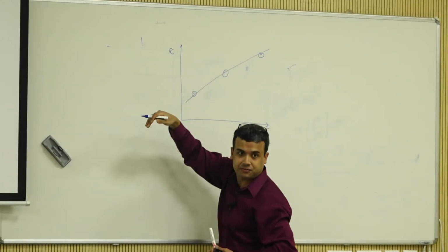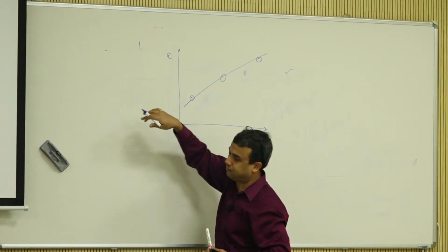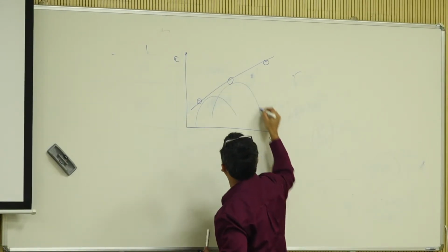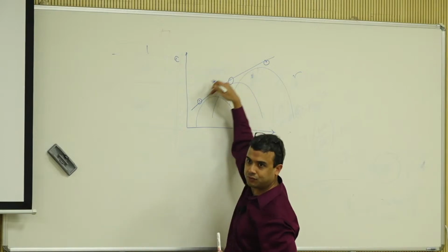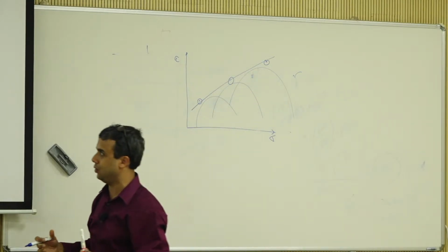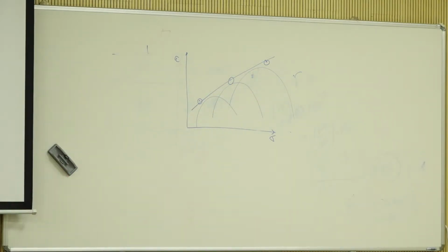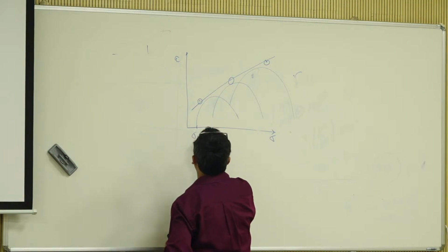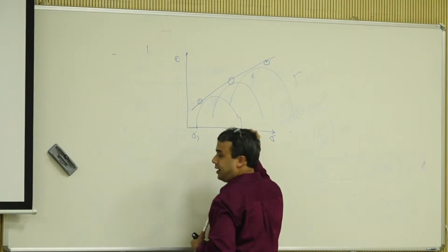That's your C versus phi, C phi. Whereas for triaxial, you have to draw more circles and you have to draw the tangent and stuff, and then you go. The point is, every triaxial test has a combination of a sigma 3 and a sigma 1, right?